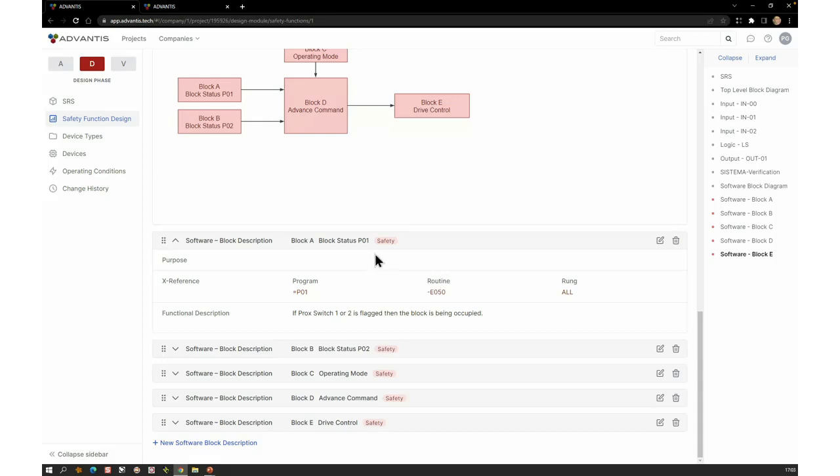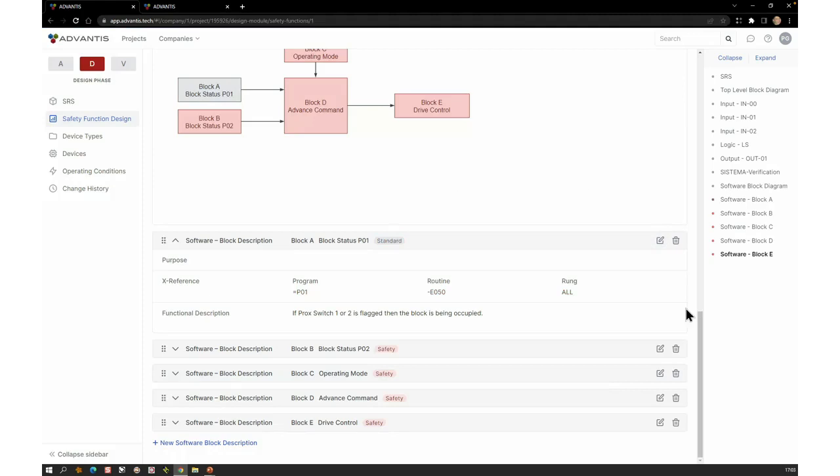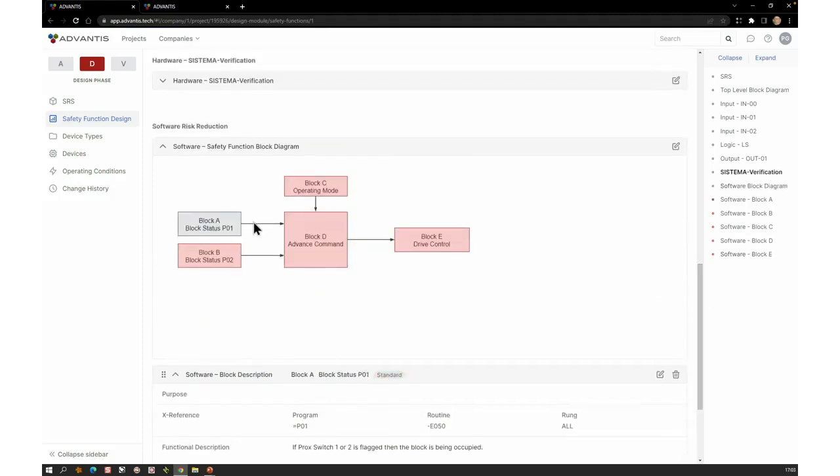One element is you have to determine whether something is in standard or in safety. If it's standard, it's gray. Sometimes certain information is mapped over from standard to safety. And that's, again, up to the reviewer to decide: well, okay, but in this safety function, we are doing a certain action on the safety side based on non-safety information. I disagree. This is not meeting the PLe requirement.